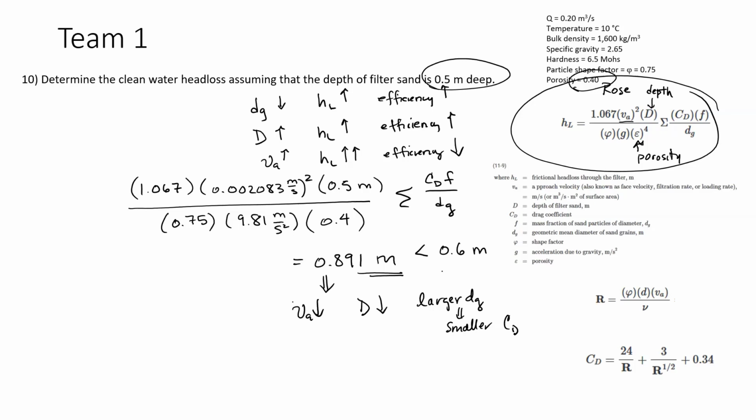So in your designs, you'll need to think about this when you go through the entire design, get to this point, realize that your clean water head loss is too great, and then think about what you need to do to deal with that.